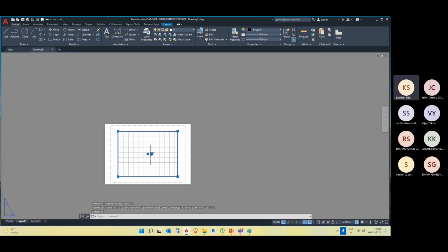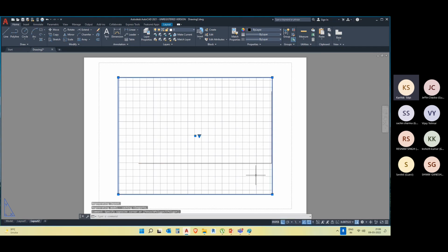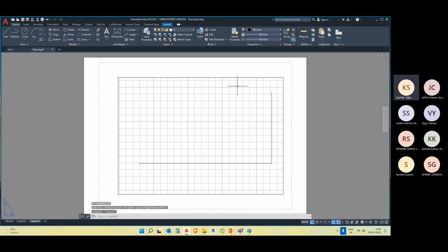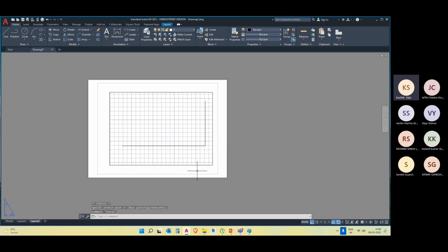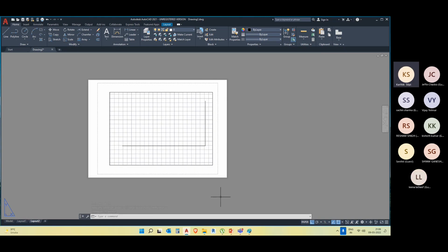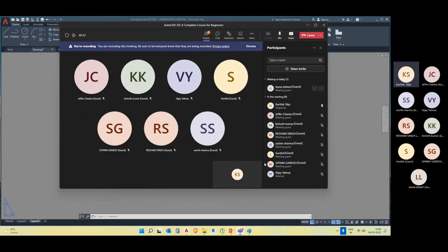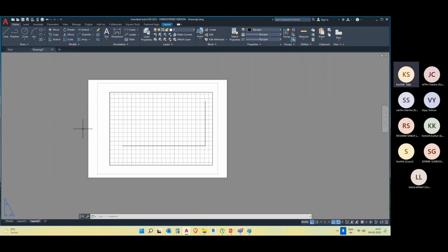Here it's not visible because I did not set the scale, but normally when you set the scale here, it's there. Right? So when we go to that scale concept, I'll explain what scale is. Here you can see that line is visible in this paper space. So we have to print the model in the paper space, whatever we draw, right? It is possible to convert either in PDF, or you can actually print in DWG format, or directly you can send to your printer. These things are always possible in the paper space.